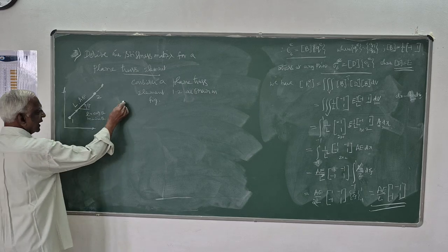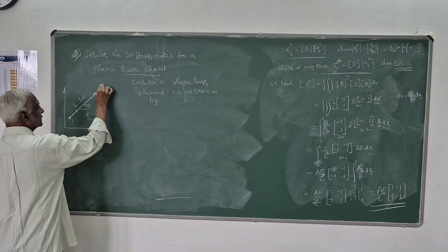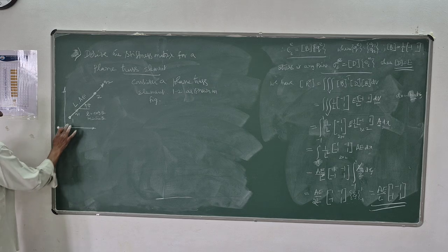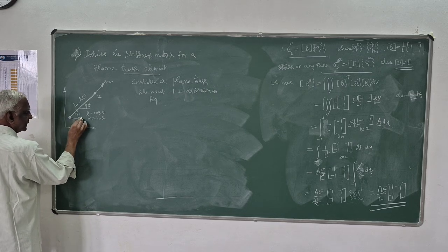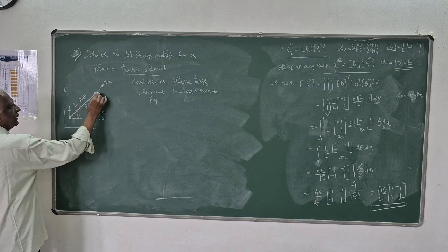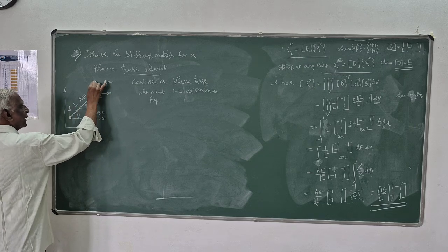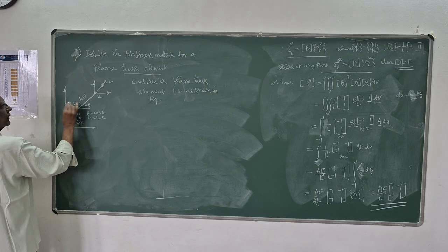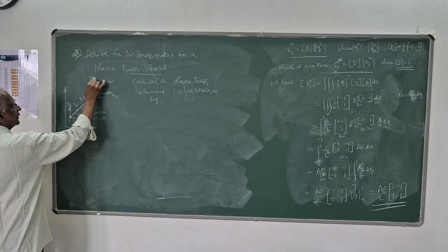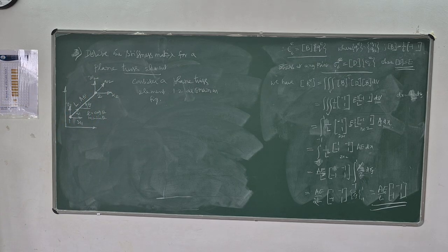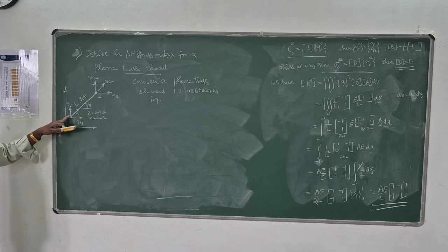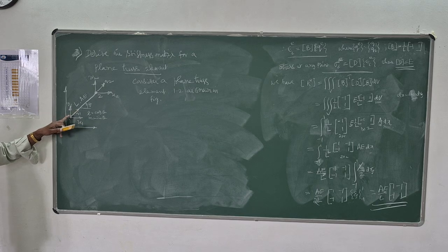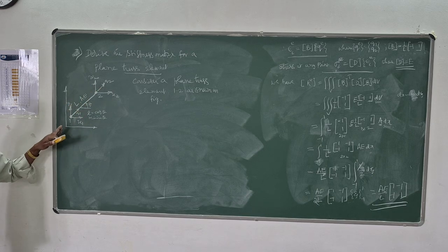If you take the same element, the local displacements are Q1, Q2, and in global coordinates the displacements will be 2 per node: U1, V1, U2, V2. Q1, Q2 are the local or natural nodal displacements along the axis.